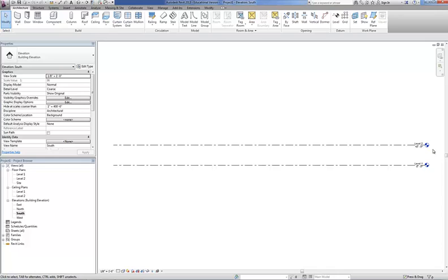And so here we're going to look at creating new levels and modifying the levels that you already have. Now this process can be done anytime, but it's a good idea to establish all of your levels that you know about at the beginning of the project so that you can then anchor various Revit objects to those heights and maintain some organization with all of your objects that you're going to install.